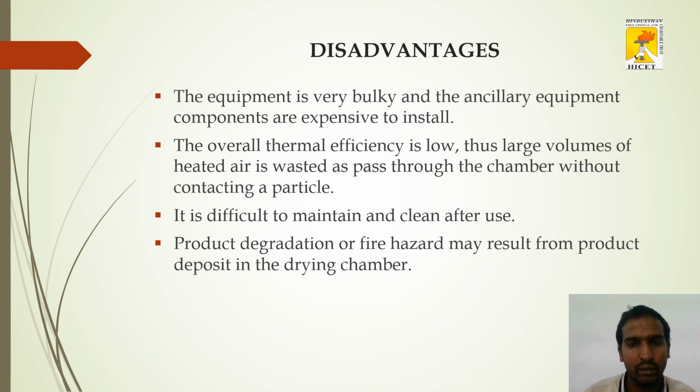And also the thermal efficiency. The thermal efficiency indicates that the air which is going outside through the exit air may contain some amount of heat. So that heat can be recycled and utilized for further pre-heat treatment to reduce the moisture from 80 percent to at least 60 or 50 percent, so that the spray drying process will be more efficient, and from the energy consumption point of view it is also more efficient.